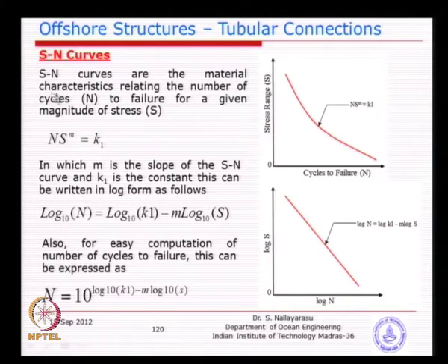So, it depends on a constant, that is what we wanted to use. If you can rewrite this whole thing in terms of this, it will be very handy, because when you are solving a problem you need to calculate the number of cycles given the stress range. This is calculated from your previous analysis by applying loads, calculating the loads and stresses, and multiplying by the stress concentration factor, you get the stress range.